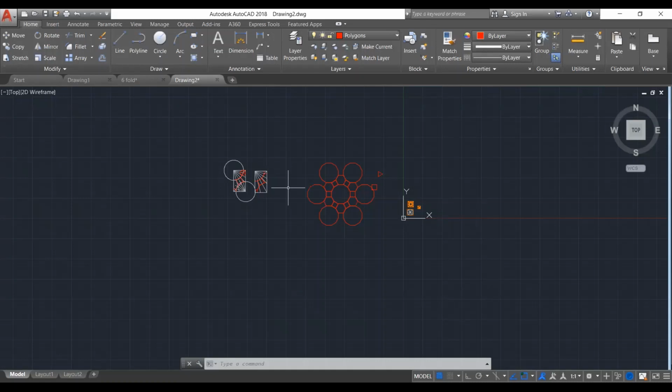Mustafa, you said that if we're going to print it, the technique is different than if it's laser cut? Yes. For the laser cut, you must do it in a double line, and you should make the double line between the pattern and the border also, in order to avoid the product being separated from each other.